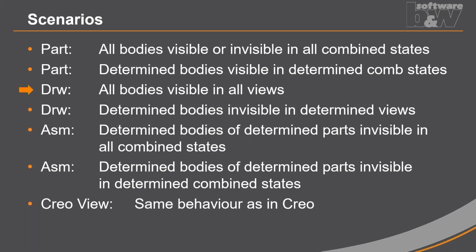In drawing mode, I have, I think, the most obvious case. I want to see all my bodies in all my views. That's, I think, the case in more than 95% of drawings. But now with the multi-body, you could imagine having a drawing of a part that has views that contain all bodies and other views that contain only a portion of the bodies.